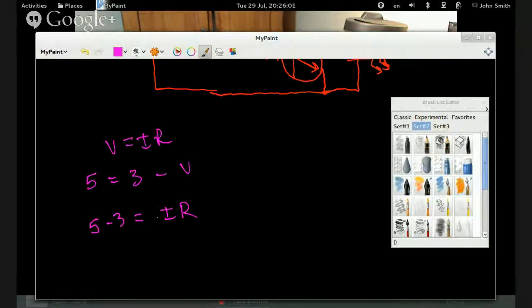And remember that with this particular LED, I know from the data sheet it needs 30 milliamps or so. So we want to limit it to 30 milliamps. Let me think this through. Actually, 50 milliamps would be good. That'll work out nicely. Yeah, let's be on the safe side. Do 20. So 2 volts equals 20 milliamps, which is 0.020 amp.